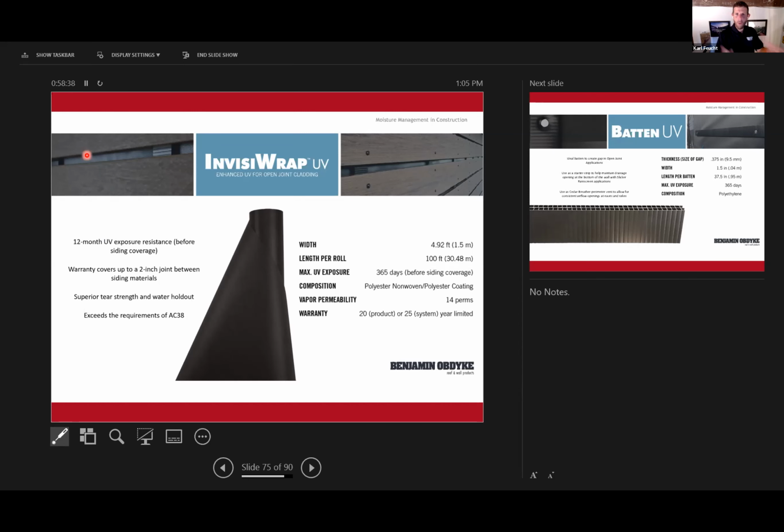You're just inviting water to get behind your siding by leaving that gap open. And the person who I said that to commented about that too. They said to me, Karl, you're thinking of your siding the wrong way. Siding is decorative. It's aesthetic, right? What goes behind the siding is what really counts. And so we've got a great system for this.